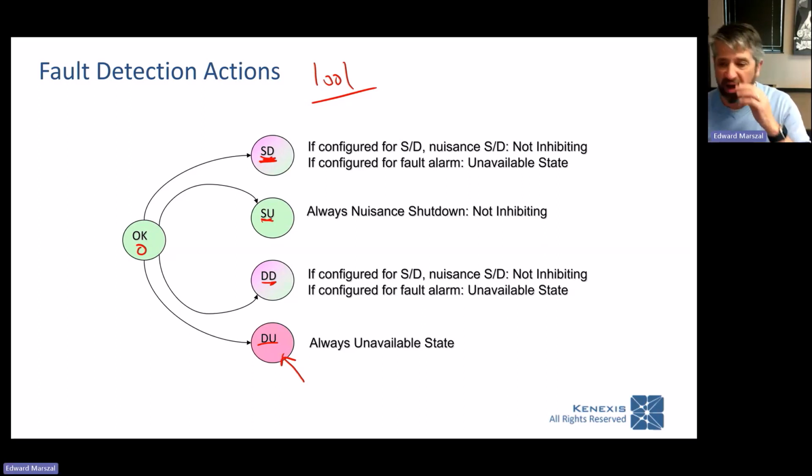That's kind of common terminology in DCSs. So if I have a bad PV, what do I do? If you continue to operate, you have made that bad PV dangerous and an unavailability. If you shut down, you made that bad PV a spurious trip.